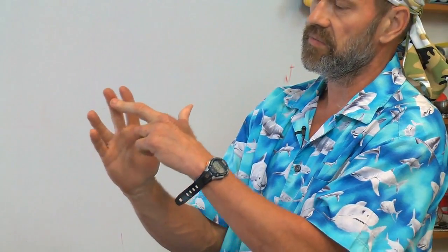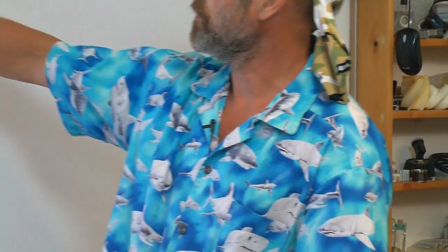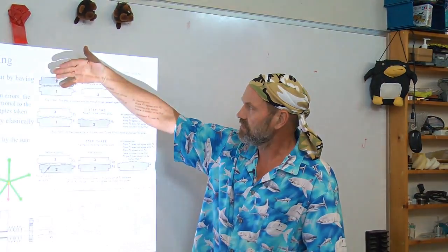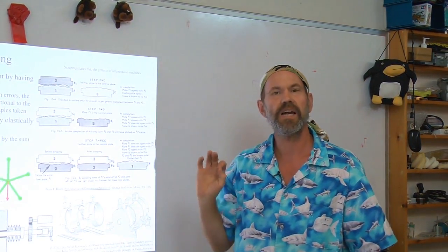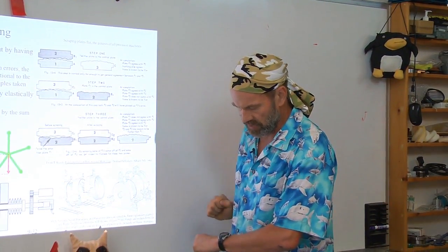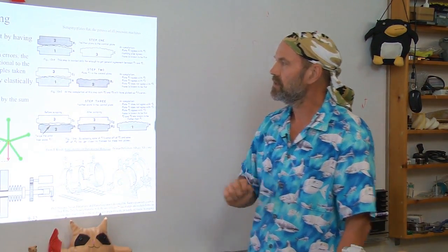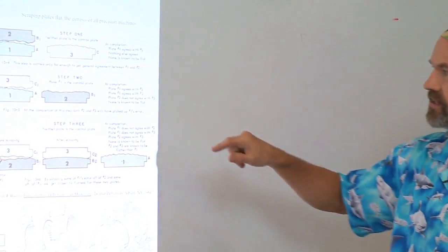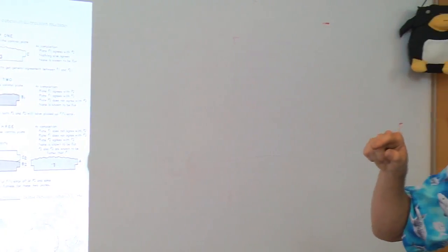You can't see it too well, but you see a little bit of brown on the finger there. It comes from it, and you can see here where it's been transferred from here to here. You can take two surfaces, put some coloring on one, put it on the other surface, rub it, and you'll transfer some color from one surface to the other that will tell you where the high points are. And that was a tool then used, a scraper, that looked like a razor blade, to scrape off the high point and repeat the process. And with three plates in a round robin scenario, you could take three huge plates even and very slowly, carefully get them flat to within a few microns.